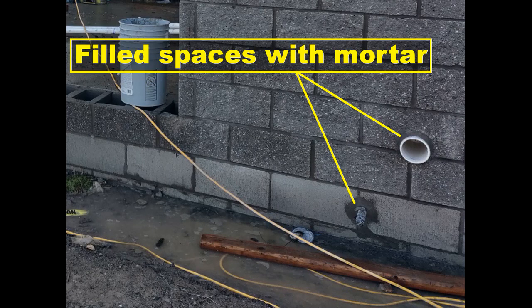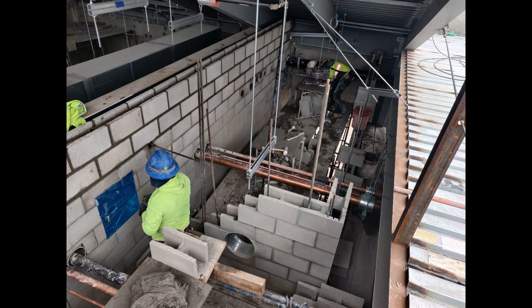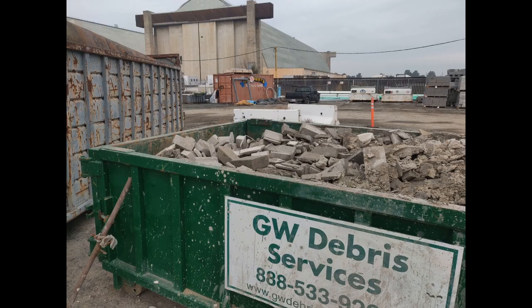Built-in items. Fill spaces around built-in items with mortar. Point openings around flush mount electrical outlet boxes in wet locations with mortar. Embed anchors, ties, wall plugs, accessories, flashing, pipe sleeves and other items required to be built in as the masonry work progresses. Fully embed anchors, ties and joint reinforcement in mortar. Fill cells receiving anchor bolts and cells of the first course below bearing plates with grout, unless otherwise indicated.